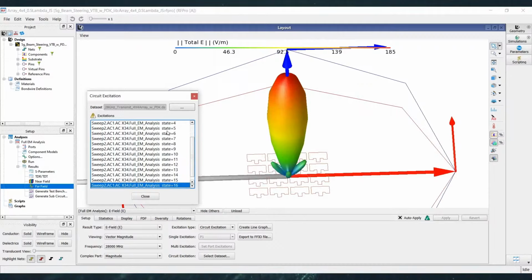Well, we can use the exact same technique in the simulator, and we can save tons of time. You can all of a sudden start optimizing this thing. Instead of needing to virtually demodulate your signal in the simulator, now you can just run it through a function, this distortion EVM function, and you can really quickly calculate error vector magnitude. And that opens up this whole world of being able to optimize, drive down the error vector magnitude in your simulation. And we're seeing that in a lot of areas, particularly driven by 5G. So that makes sense. It seems like simulation would be super handy there.